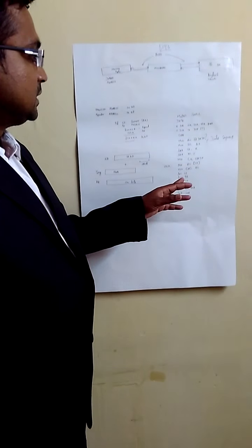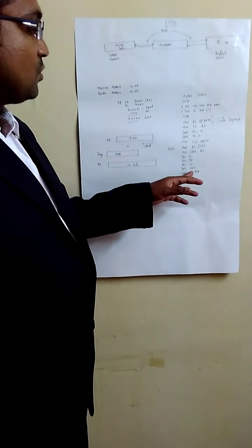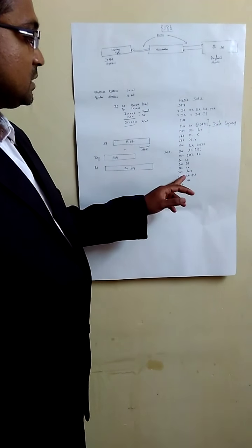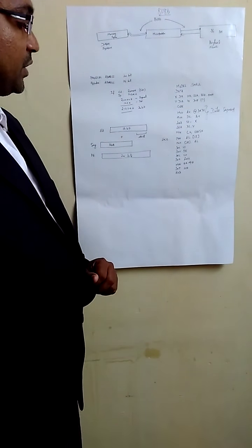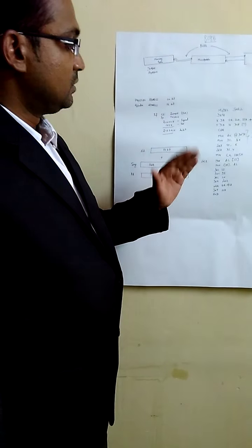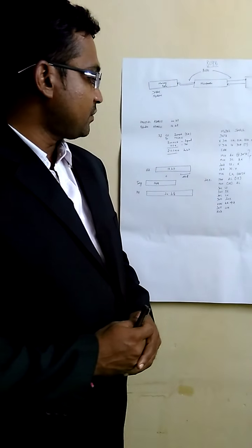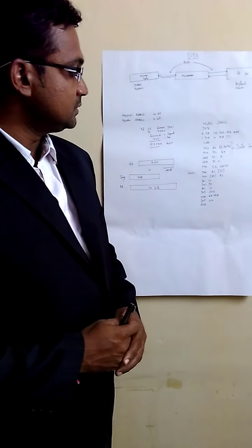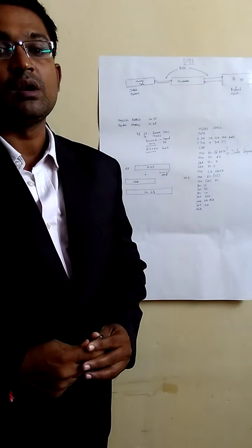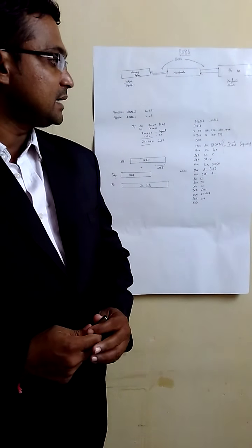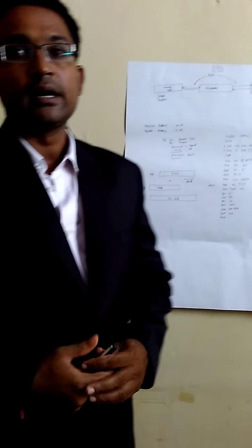After the CX becomes 0, the 4 values have been copied. Then MOV AH, 4CH is the value we are loading, and INT 21H we are calling to end the program. After that, for the assembler, we are using the directive called END to end the assembler instructions. Next we are going to see the interrupt concept.